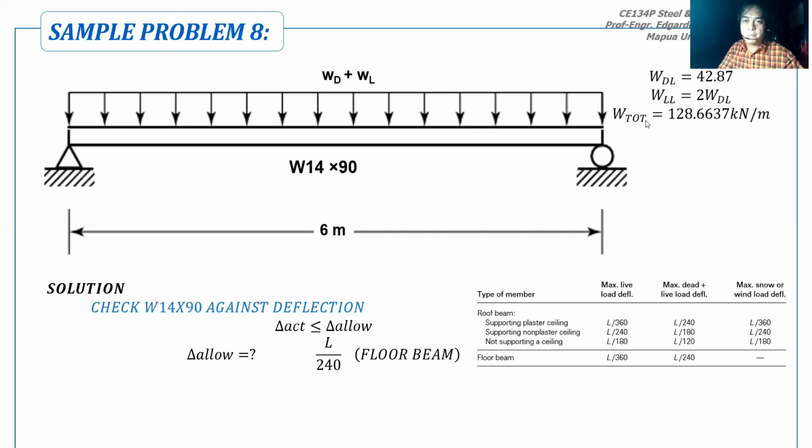As per the table, the maximum deflection would be L over 240. So that is the allowable deflection.